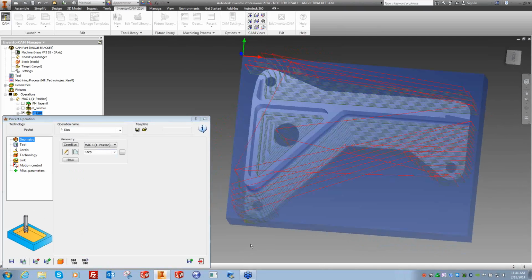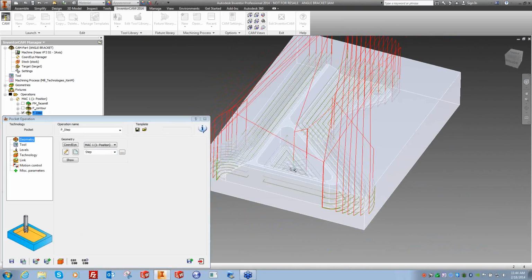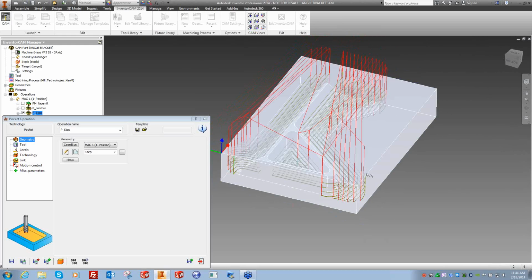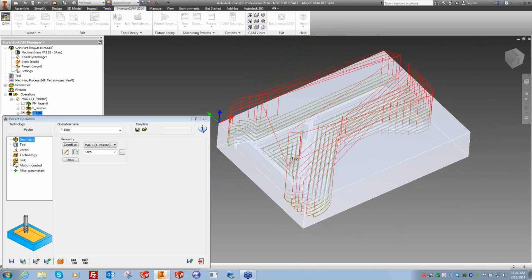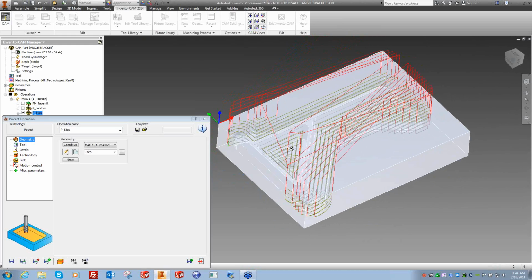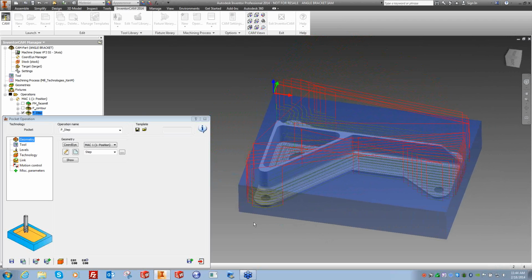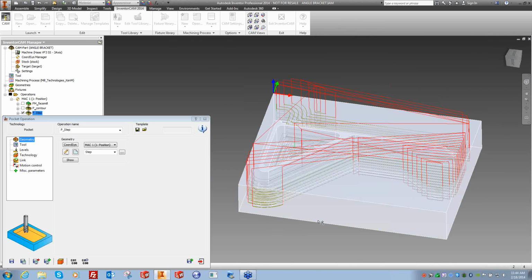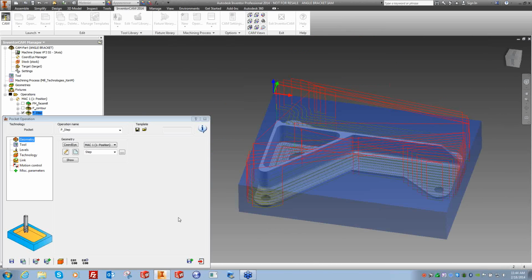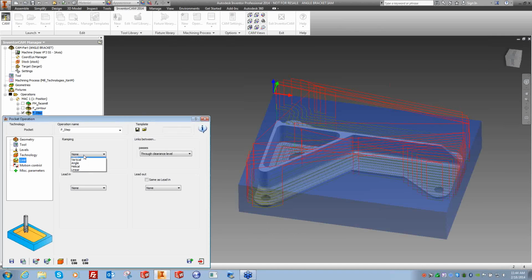Now we have toolpath in the middle. However, you notice that it's plunging straight down because that's what it's doing off the sides of the tool. We actually want a helix, but we want a helix just for this pocket, not for the rest of them. It'll automatically figure out where it's at and know where the material is, especially since we use 3D model for our stock. So I'm going to come down to my links, and I'm going to turn on helical.